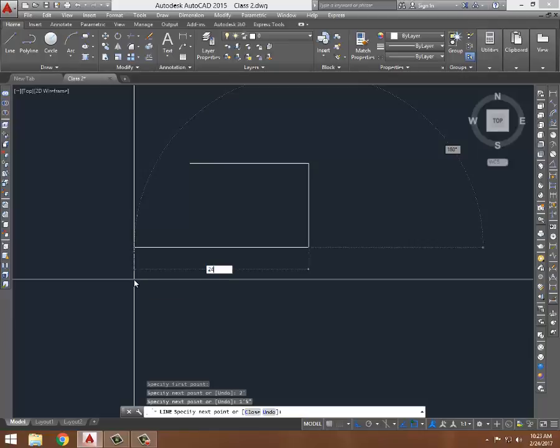I just want to tell you everything about those lines, so you're not scared or confused about why I have to do it this way or that way. For the line above I provide 2 feet, and for the line on the side I provide 1 feet 5 inch, and now I'm providing 24 only, because if I put 24 I do not need to put inch or feet, because our unit is inch, so AutoCAD knows 24 and I just press enter. So this is my third line.